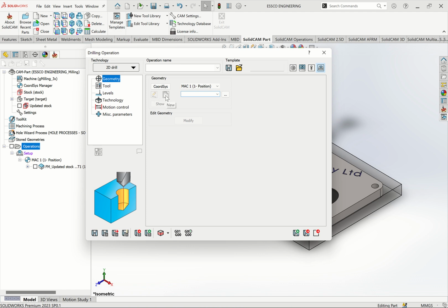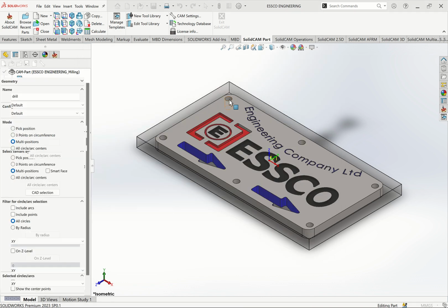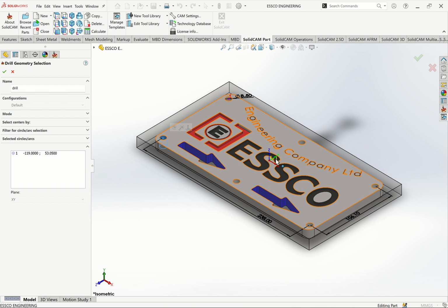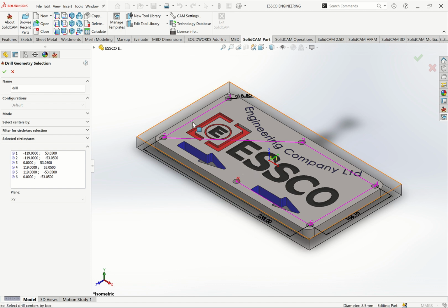click new geometry. Where are we going to do our drilling? So click drilling, new geometry, you click those faces, for example, these faces. I'm doing this part, but I've not done chamfering, I'm just assuming for that case. Then these are the parts you put on the machine. So number one is this, number two, something like that. So we have six holes, and these are the coordinate systems. The machine will be following this to read. That is x and y, x and y.